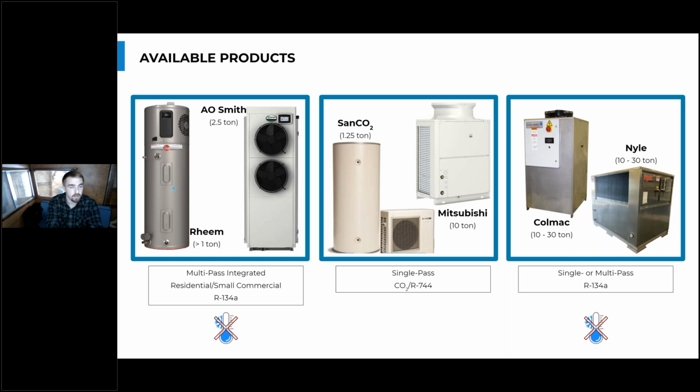The next product category is the single pass CO2 heat pumps. And we put this in a category by itself because they have some pretty specific capabilities compared to these other more conventional refrigerant heat pump water heaters. And they can operate in really low temperatures because of how their refrigerant works.